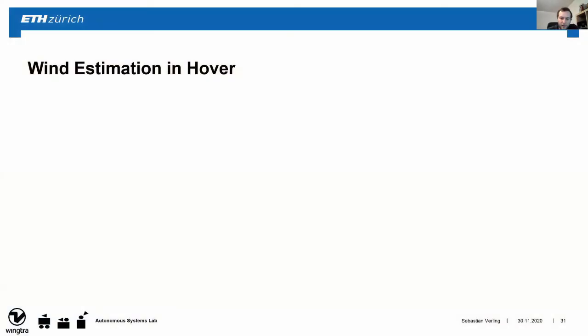So that was wind between 4 and 8 meters per second, to kind of get a relation for this. Now, in order to overcome this problem, we first tried to find a way of estimating the wind, because the more you know, the better generally. A typical approach to estimate uncertain quantities is through means of Kalman filters, which is also what we then did.